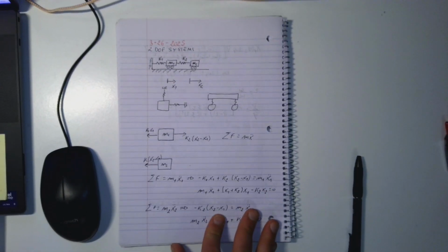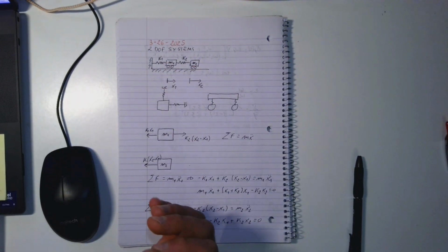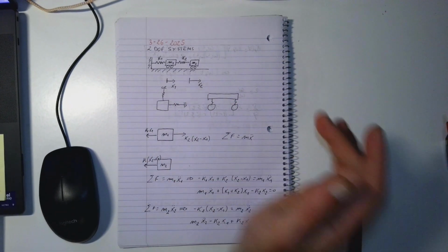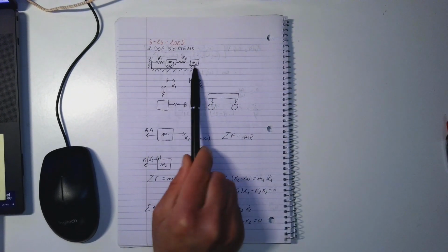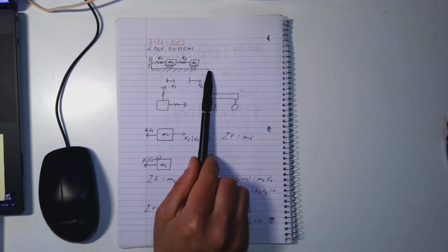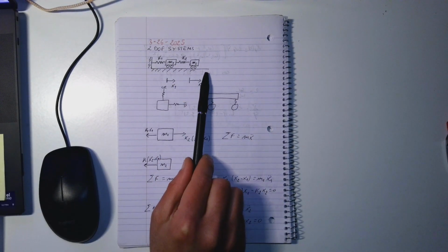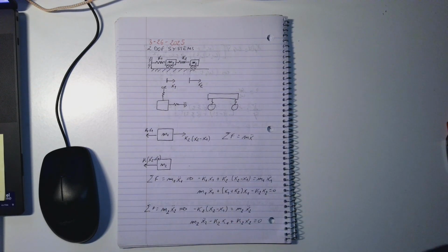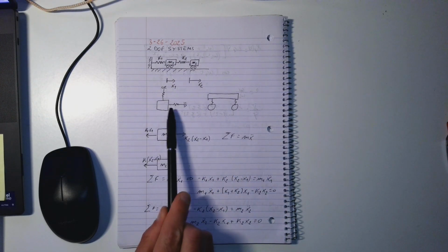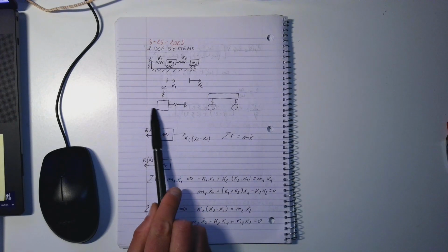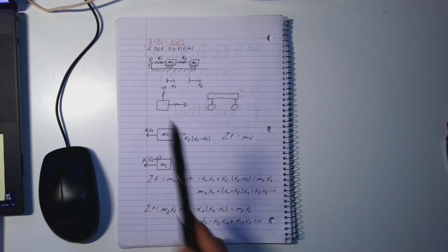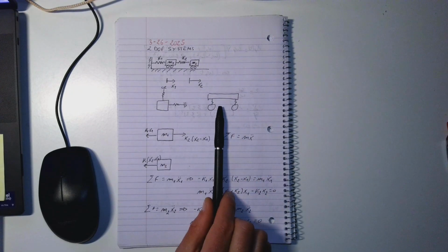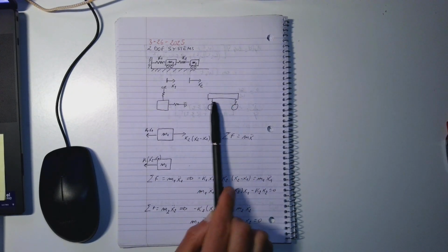We also specified that we need to pay attention in order to determine the number of degrees of freedom, because in this case it seems obvious that with two masses that can move independently from each other we have 2 degrees of freedom. However, we can have 2 degrees of freedom even if we have only one mass. For example, in this case, if the mass can move horizontally and vertically, it means that we still have 2 degrees of freedom. Or we looked at the example of the car with the suspension.